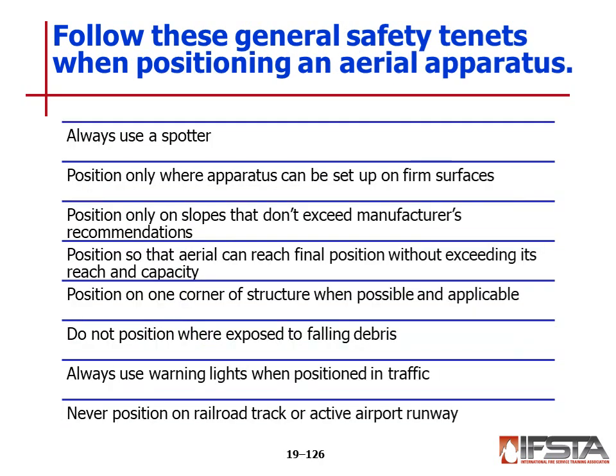Always use a spotter. Position only where apparatus can be set up on a firm surface. Position only on slopes that do not exceed manufacturer's recommendations. Position so that the aerial can reach the final position without exceeding its reach and capacity. Position on one corner of the structure when possible and applicable.